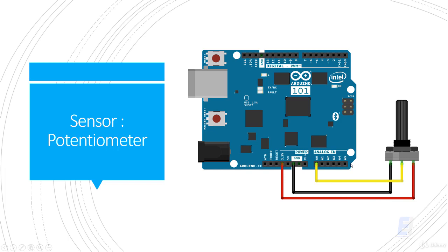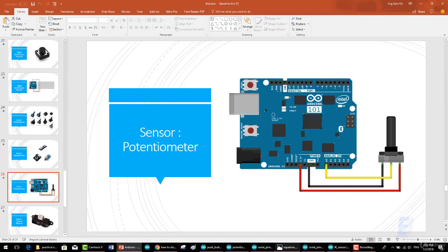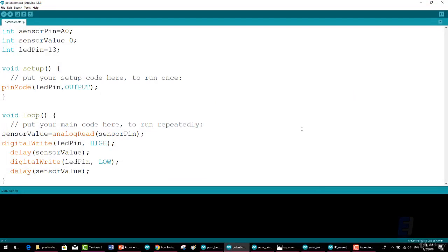Now, I will show you and explain every line of the code which is required for this lesson. We will start by initializing the variables as before. First, int sensorPin = A0; The name sensorPin was chosen only to describe what the variable represents. The integer sensorPin is equal to A0, where A0 is analog pin 0 on the Arduino.